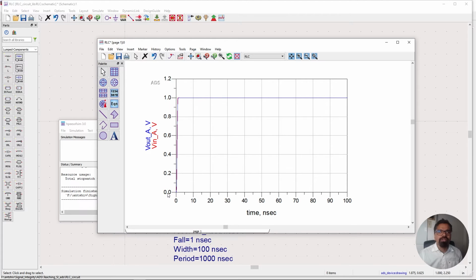So what I'm going to do is just adjust some of the things a little so that it's more readable to me. If you just click on this, you can make some changes. So I'm going to make this -1, 0.1, so there is some space before it starts, which is now looking a lot better. And since we're simulating every 1 nanosecond, the sampling is going to be every 1 nanosecond.